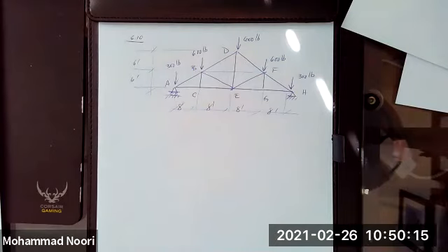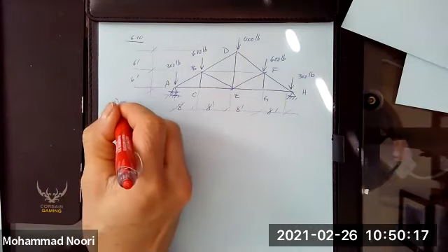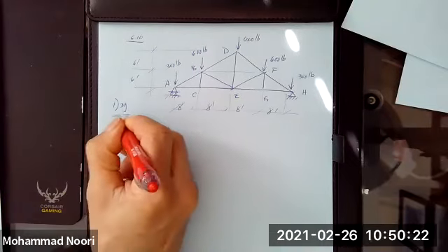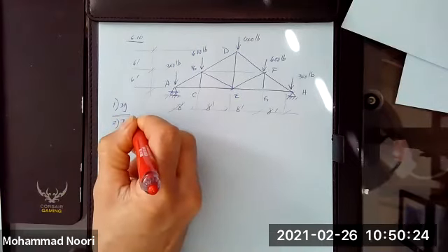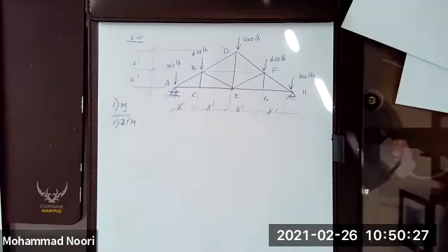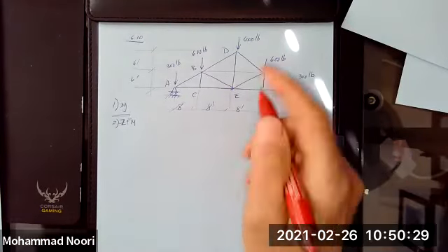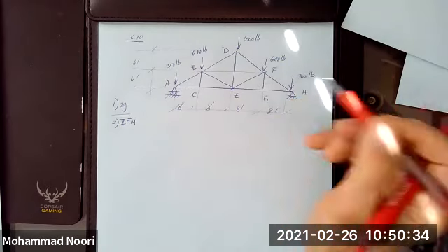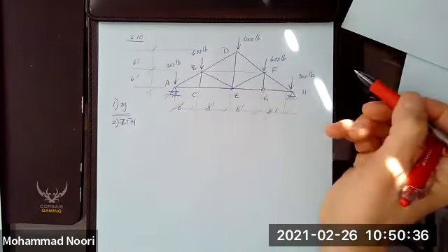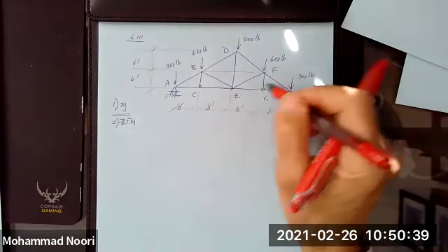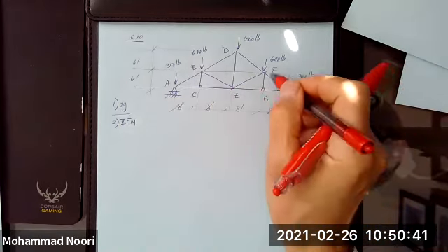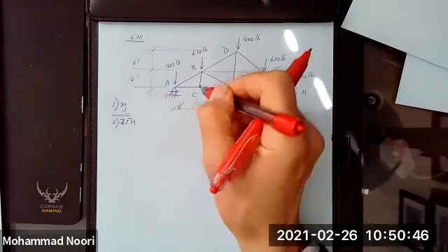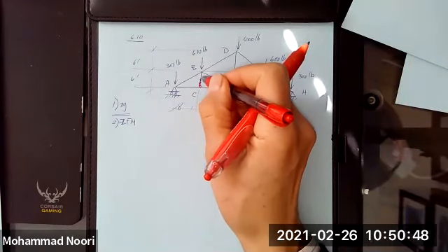I told you, of course, the procedure is that you start with setting up XY and then 0 force members. So let's complete those steps. Then I'm going to show you something very interesting. Do you see any 0 force members? Look at a joint with 3 forces, 2 collinear. So if you look at G, look at C, both satisfy those conditions. 3 forces, 2 collinear. So this one is gone. Same thing here. This one will go.